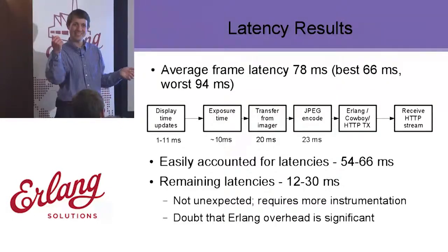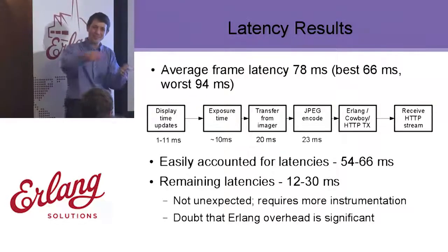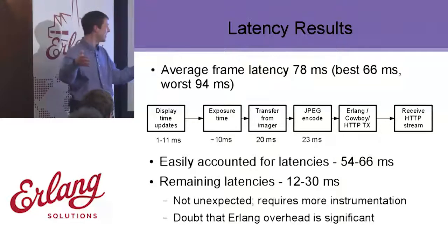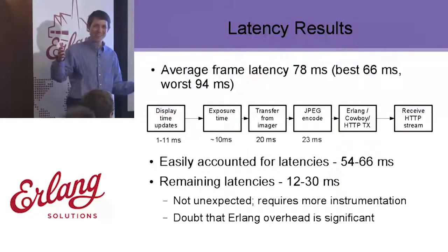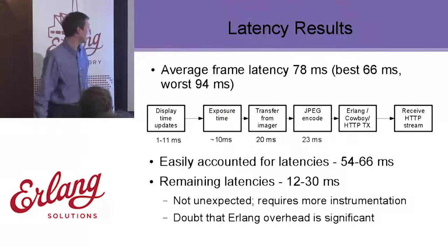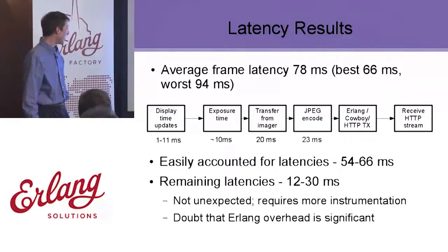It's not like these cameras expose instantaneously. The imager that's connected, you have this big parallel bus, but it doesn't go all that fast. So that actually takes quite a long time, and I could probably ramp up the clock a little bit, but it's around 20 milliseconds for what I got there. And then of course we found out JPEG encodes 23. So that's really easy accounting there.